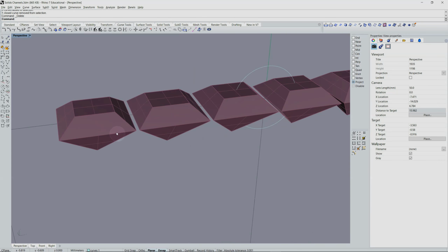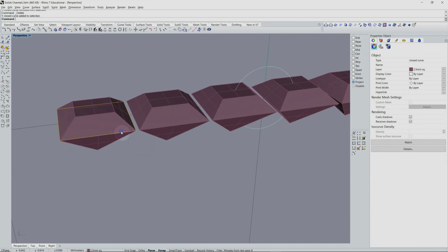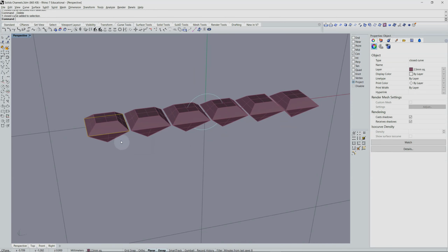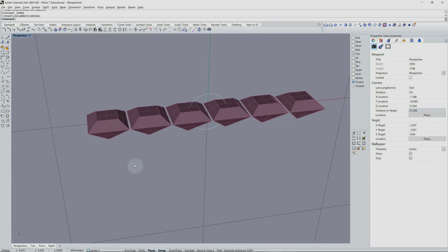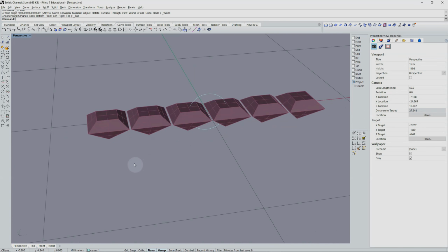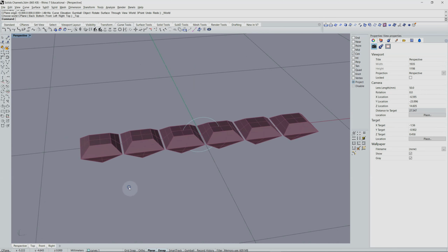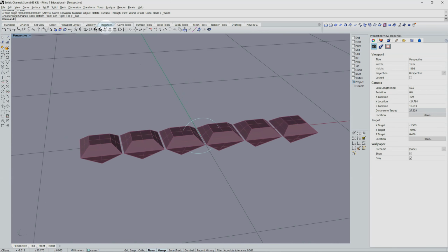Now it's time to start drawing our channel setting, beginning with the opening in the top of the setting for our stones. I will do this by using non-uniform scale to stretch this girdle from our far left stone until it reaches the full length of our entire set. I'll begin by returning to my default working C-plane, which is the top C-plane, by hitting.